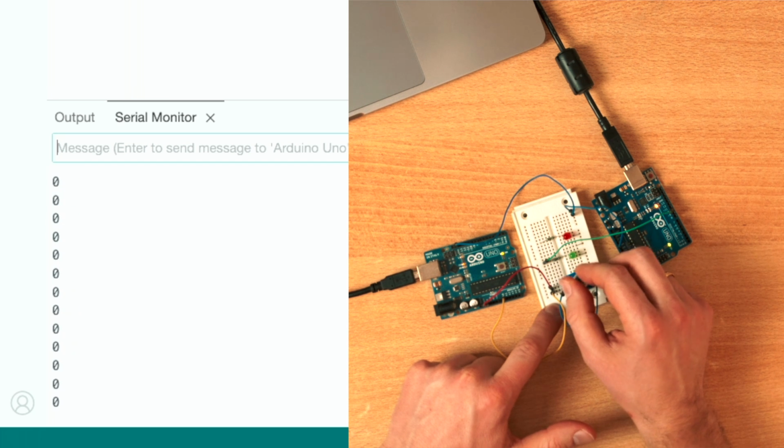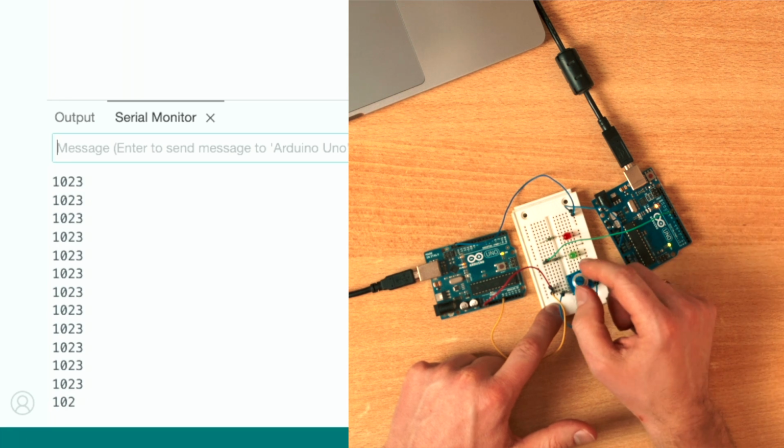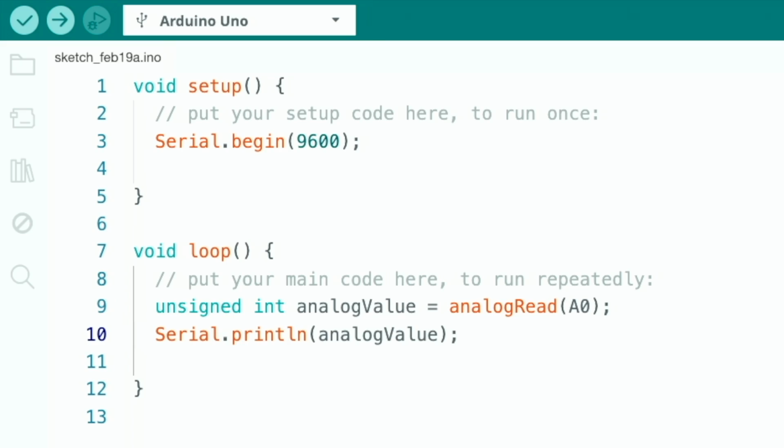As you can see, this value starts at 0 and goes up to 1023. That's the maximum number because it's a 10-bit analog digital converter. If we send it like this, we need up to 5 bytes to transmit this data. So I would like to actually do two things. The first thing is our second Arduino will generate a pulse width modulated signal, and that only has a resolution of 8 bits. So from 0 to 255. So the first thing is I will reduce the 10 bits to 8 bits.